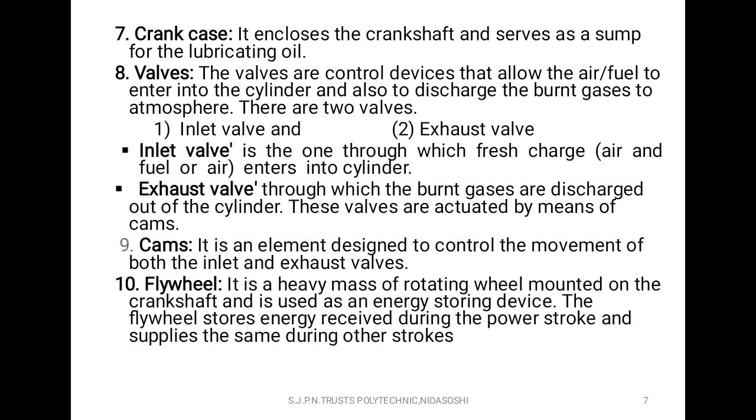It is kept on the crankshaft, and it is used to store the energy or work during the power stroke, and it supplies the energy or power required during the other strokes. This is the flywheel. So these are the important parts of the IC engine. So, 5 to 10 marks.